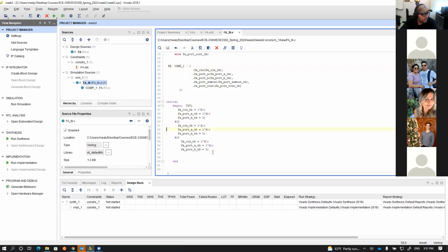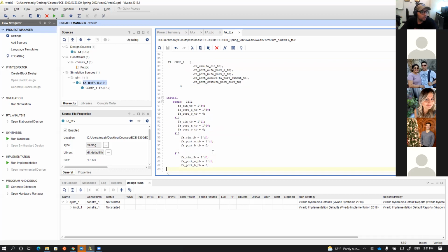Yes. So anyway, I will add a couple of cases, but you guys can later add more, because I will give you a copy of this. For instance, in circuits we have something called corner cases. Have you guys heard about it? In corner cases, we are looking for something that might generate or propagate an error. One of the cases I would like to check is, if all of them are ones, what will happen? Carry out will be coming out, right?